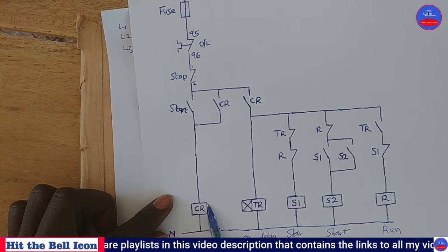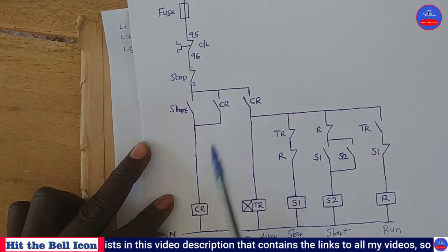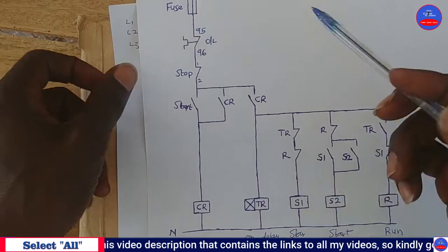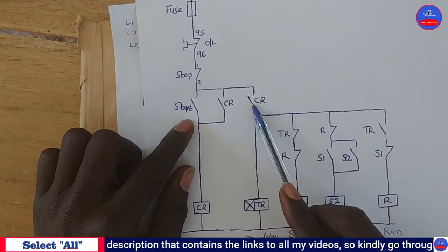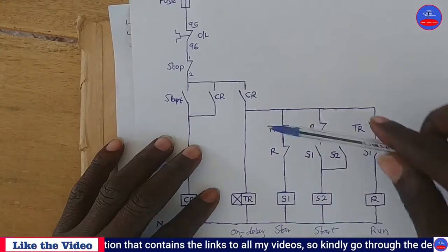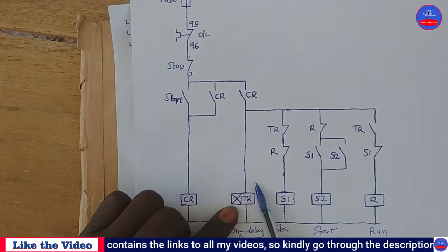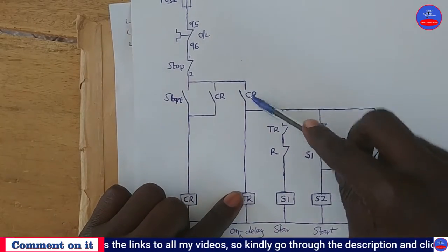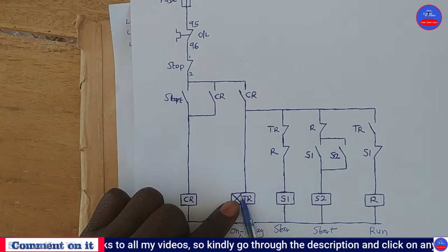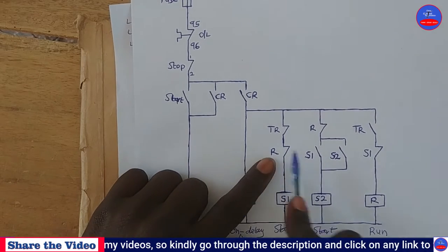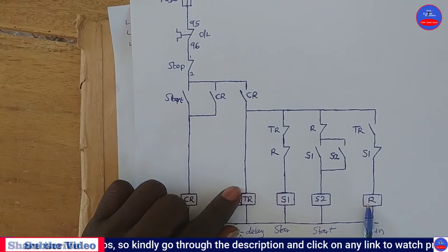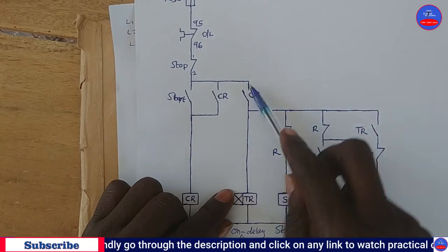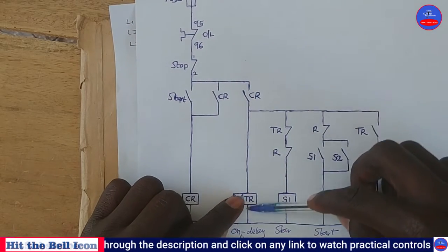All right, I use relay. So when this relay energizes, this side will close, this side will close, now allowing current to flow through the circuit. Current will flow through the timer, and then the timer will energize. At the same time, this is a closed contact on the timer. This is a closed contact on this run contactor. Because they are all closed, as soon as it closes, the timer will energize.